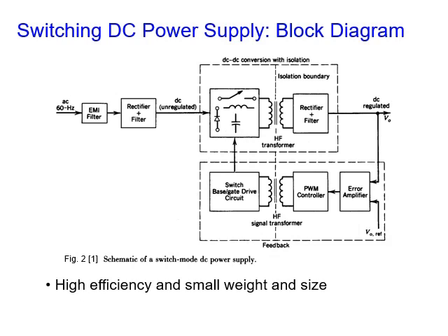You can see here the sequence. We have the AC input, as we know, rectifier and filter. By the way, we put here an EMI, electromagnetic interference filter, because we expected that there is high frequency switching occurring on the switch of the converter. So this filter is to protect from this electromagnetic interference.